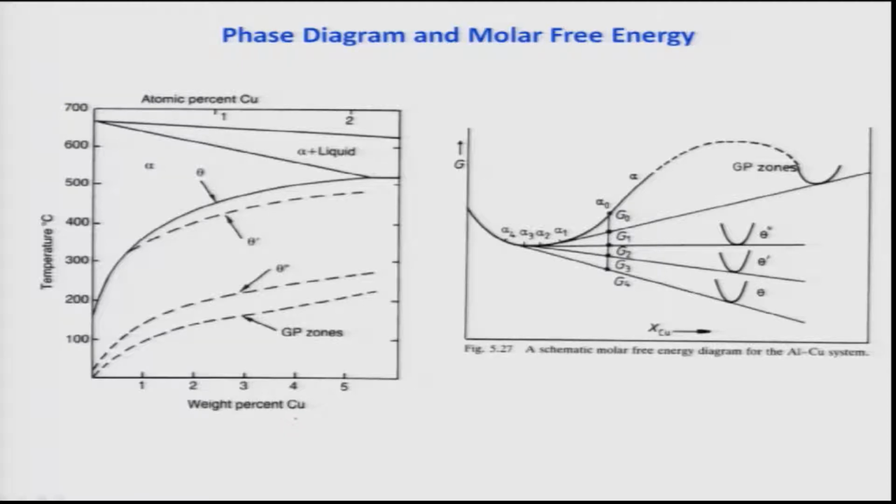And this is very important because all the theoretical backgrounds are basically based on the extensive study on this aluminum-copper alloy. The alloy which is important and widely used in the industry is aluminum 4-8% copper alloy, shown here. So simply by adding 4-8% copper, we can actually change the mechanical properties of aluminum extensively.